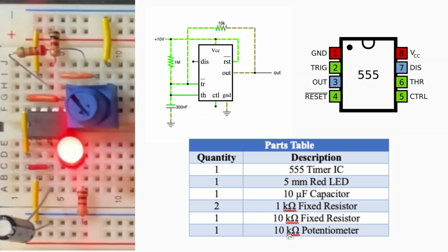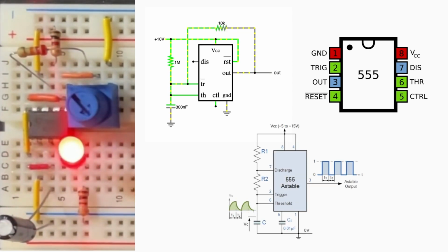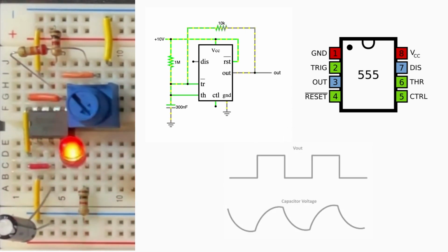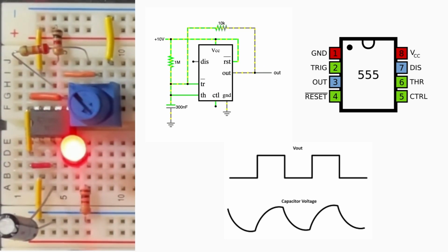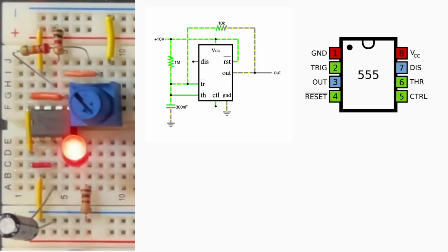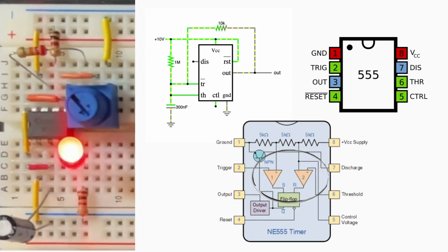The first circuit built in this project was a simple 555 oscillator using the timer in astable mode. In this mode, the 555 timer continuously generates a square wave, alternating between high and low states without requiring external triggering. The 555 timer operates with two comparators that monitor the voltage across a capacitor, comparing it to reference voltages at 1/3 and 2/3 of the supply voltage.